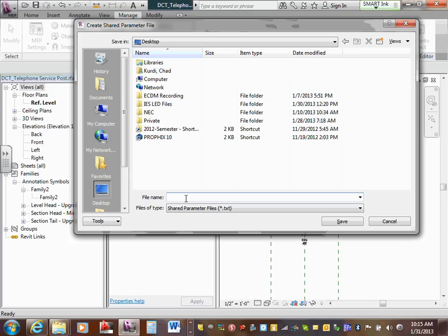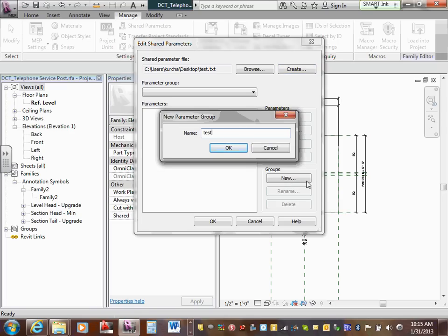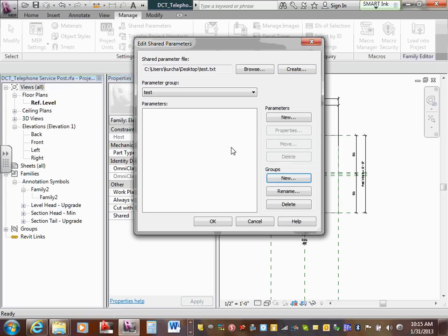I could get it to do the light fixtures, I could make a mechanical one, but I couldn't really make a light fixture schedule last time, because what they were tied to was difficult. What we're doing right now is we basically take a visual schedule, take it to CAD, and from CAD into Revit. So we're really kind of tricking them. We're not taking advantage of the parameters.